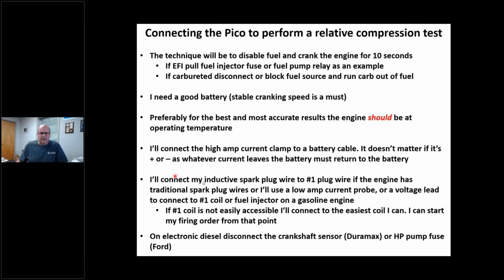We're going to connect that high amp current clamp around a battery cable. Notice I said a battery cable. I don't care if it's ground, I don't care if it's hot, because if you know electrical theory, whatever leaves the battery has to come back. If the ground side is the one staring me in the face, that's where I'm going. If the hot side's right there, that's where I'm going. I'm not prejudiced when it comes to battery cables. I'm going to whichever one is the easiest.